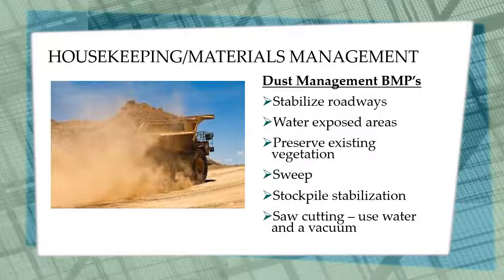Dust management BMPs include stabilizing roadways. This is typically done with a water truck. Also, watering other exposed areas, preserving existing vegetation, sweeping, especially at the construction entrance, stabilizing stockpiles, and saw cutting using water and a vacuum.